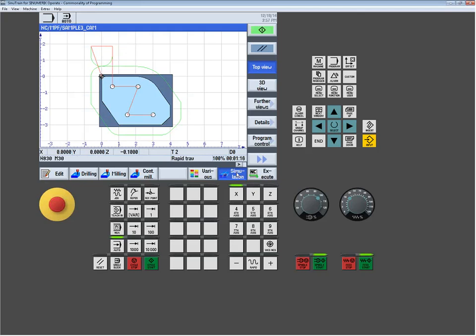Now we're breaking through. Okay. Now the other method I wanted to show you is, let's say this was the job you were sent down, and now you wanted to add a new operation. Maybe I looked at this and said, you know what, I want to center drill those holes before I drill them, but I don't want to have to worry about getting my CAM department involved or doing all the steps it would traditionally take to add it.